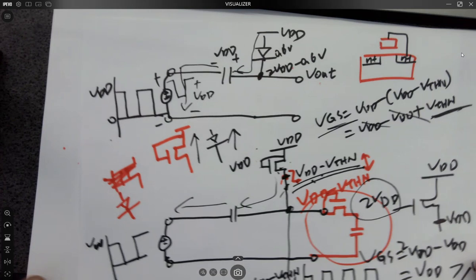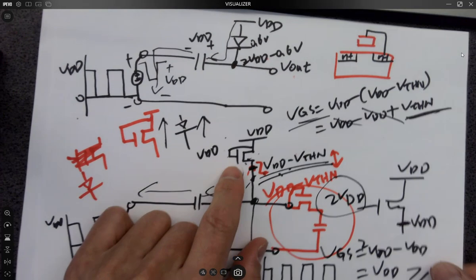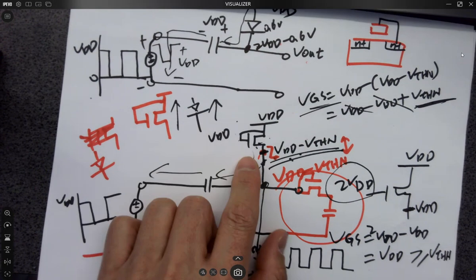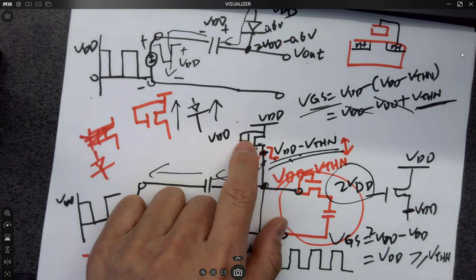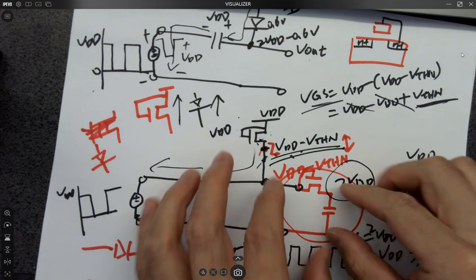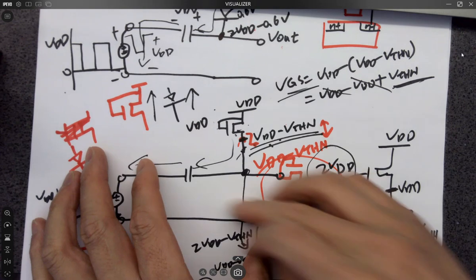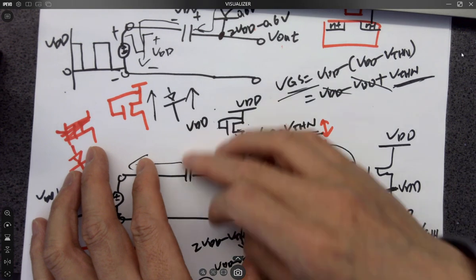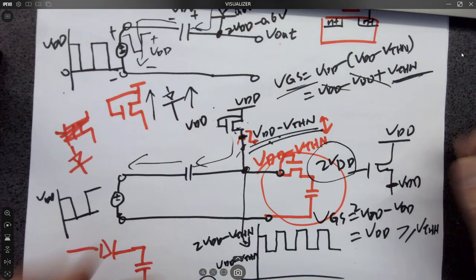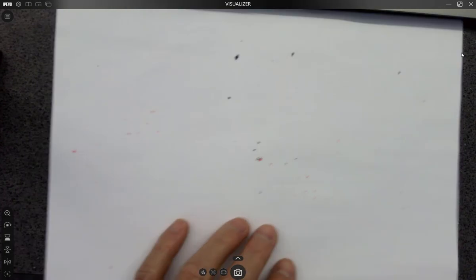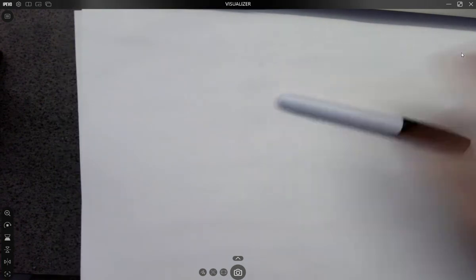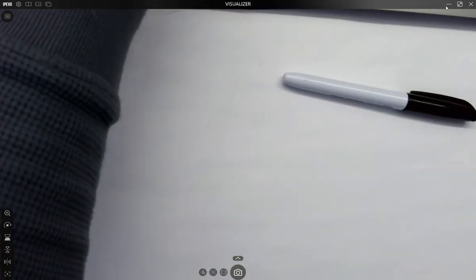We can use transistors because it's more of a standard way to build highly integrated circuits. So we prefer to use these transistors to build the charge pumps like this. And you can add more stages to this structure, forming the Dixon charge pump. Eventually you can look at your notes from Monday for what that charge pump looks like. After we understand how the charge pump works, we can run a quick simulation before we get into the whole sample circuit.